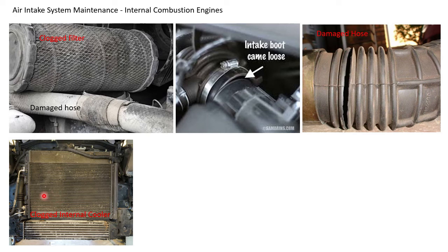Sometimes the internal clogging also will be there because of various reasons. Even the internal clogging of the tubes also leads to poor heat dissipation, causing again overheating of the engine.